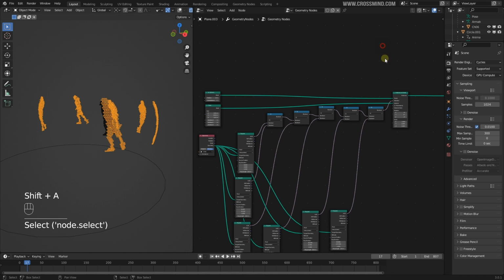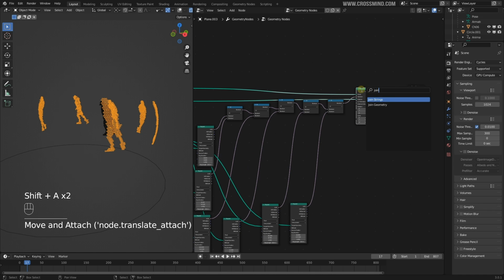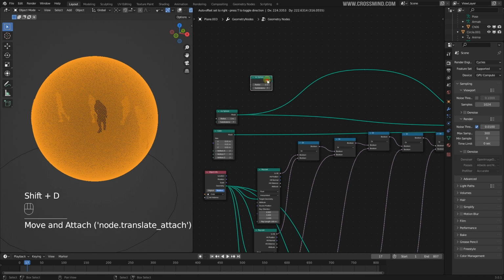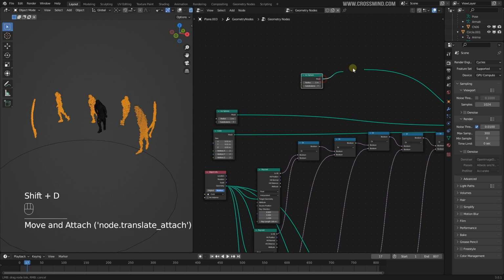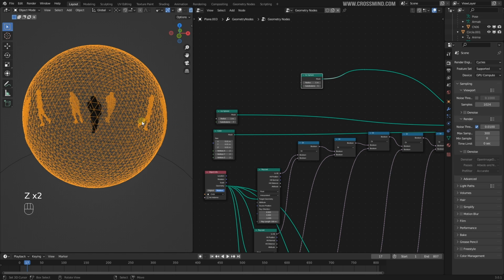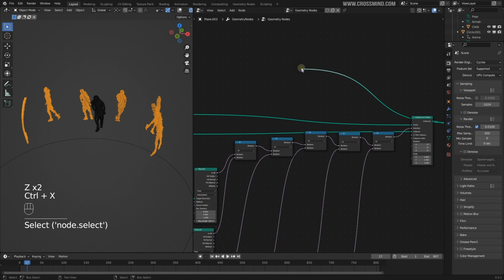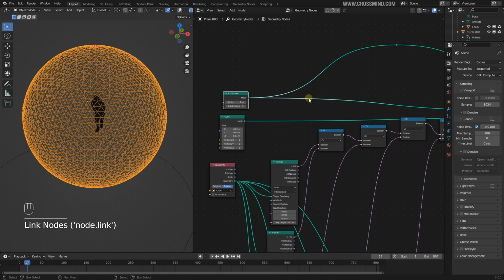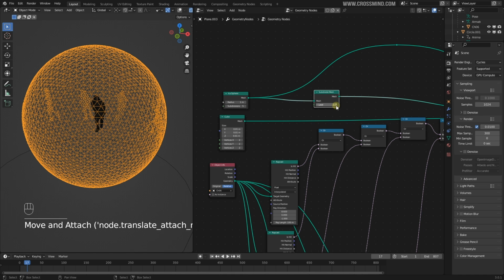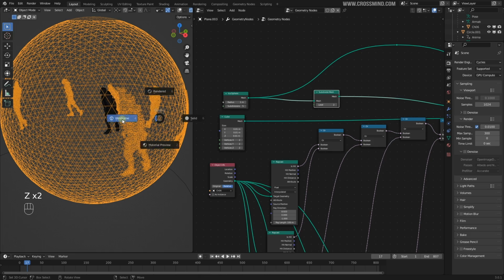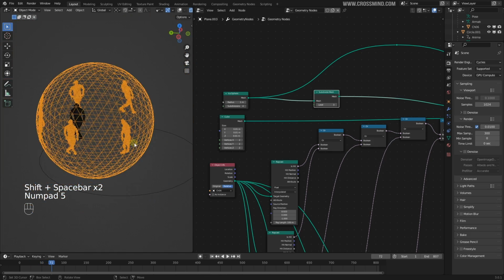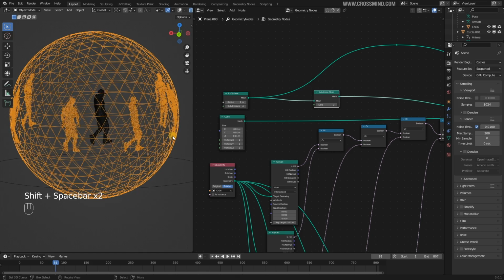You can combine the original glass input with the joint geometry and plug that here. Maybe you can make a duplicate of the original geometry and plug that here and reduce the resolution because we don't really need so many points. Or a much simpler thing, we can reduce these numbers and subdivide this mesh here. There you go. So you have instances now in multiple directions, and this looks fine.